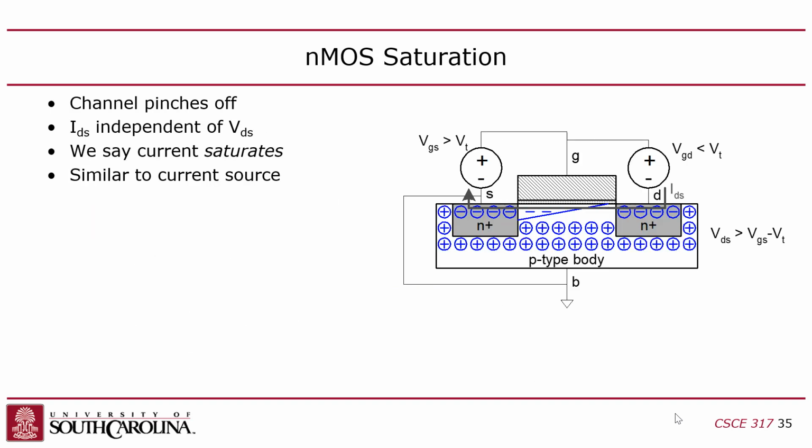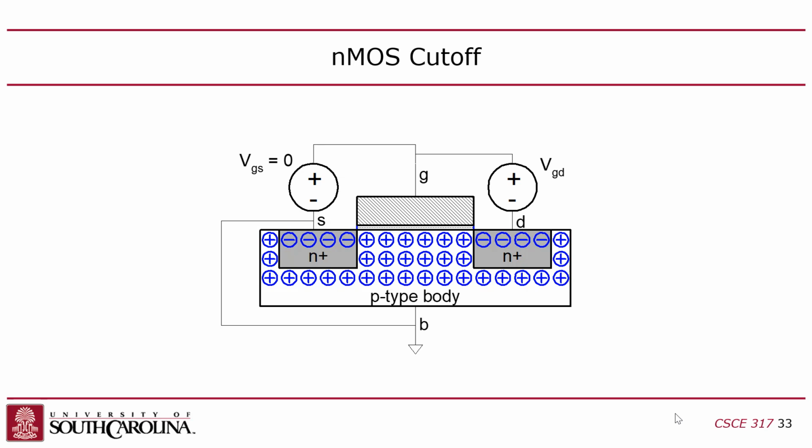The thing to understand here, well, there's a couple of things actually. There are 3 operating regions. There's the cutoff region, which is where the transistor is turned off. That's when the gate voltage relative to, in this case, the body, the substrate, is less than the threshold, which is usually around 700 millivolts. So that's the cutoff. That's when the transistor is off.